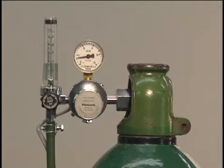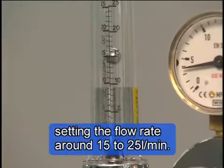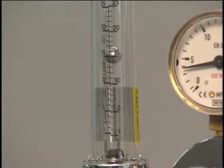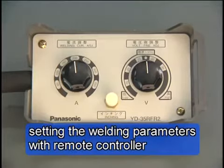The shield gas flow is adjusted to 15 to 25 liters per minute by the gas regulator. The gas should be without moisture per the JIS specification. Welding amperage and arc voltage are set by the remote control.